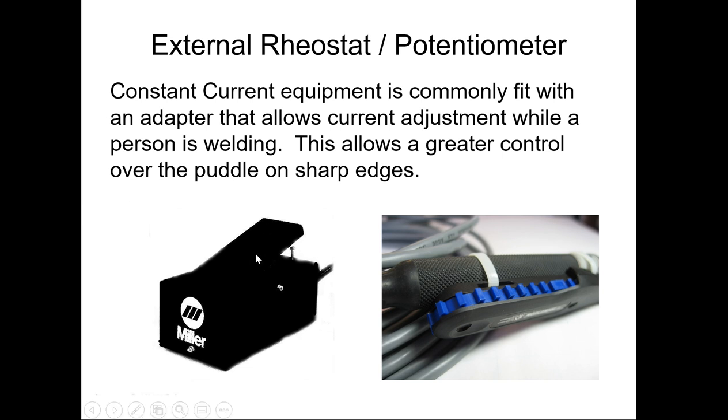One of the exercises I'm going to give you is a crater control exercise where you're going to just start welds and end welds right there on the same spot, and you're going to make little tiny pyramids of material. This is to check and see if you know how to fill a crater continuously without stalling the arc, because we want to get the arc established and then we want the arc to shrink as we go. And these are things we can do.